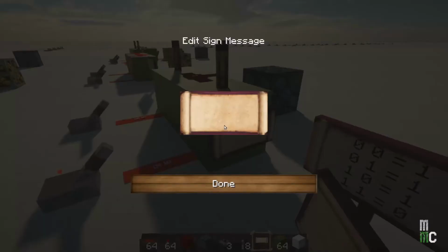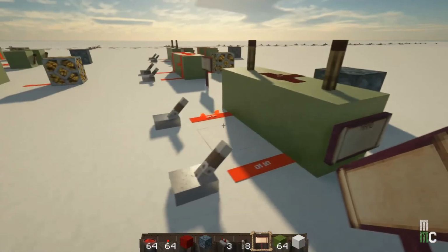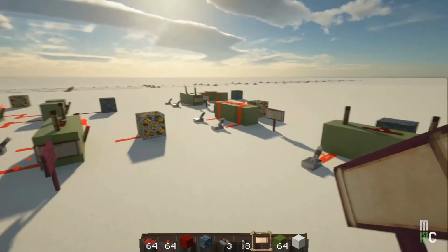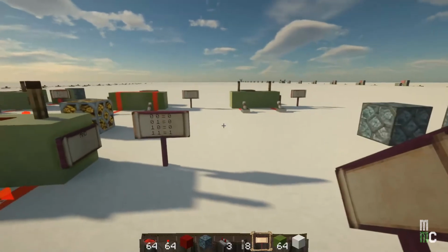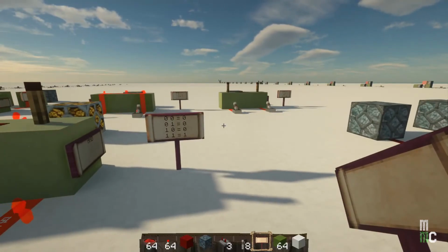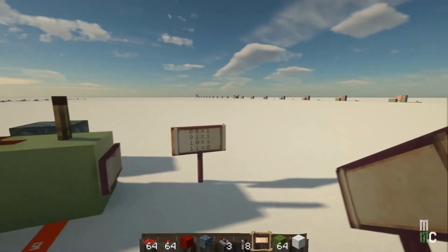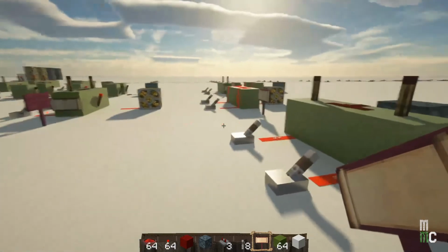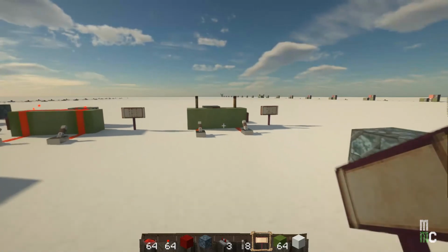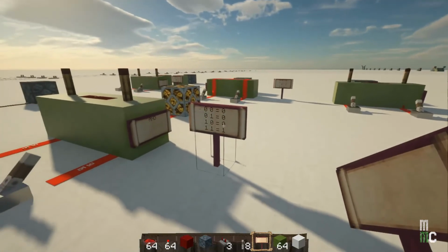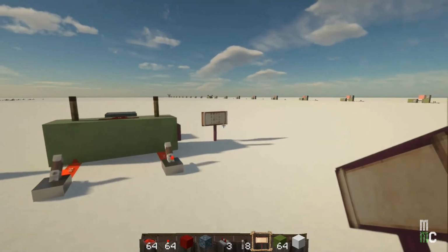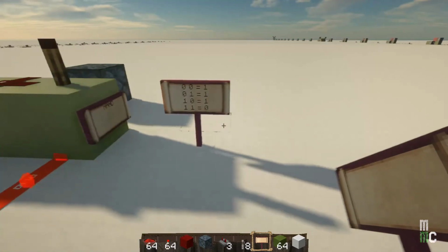This is called the NAND gate. A negated AND. Like so. And if you look at the opposite between it and the AND gate, you'll see it's exactly the opposite. 0, 0, 0, 1. And then down here you have 1, 1, 1, 0. So you can see that's the opposite, because the difference is we did not negate.